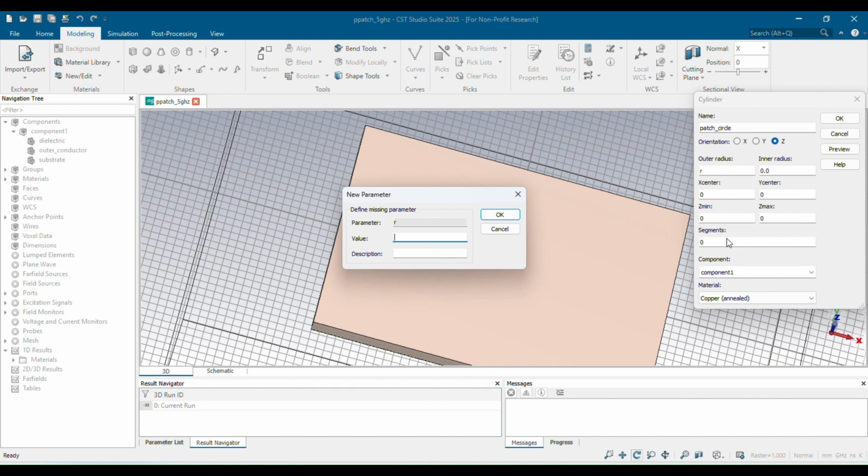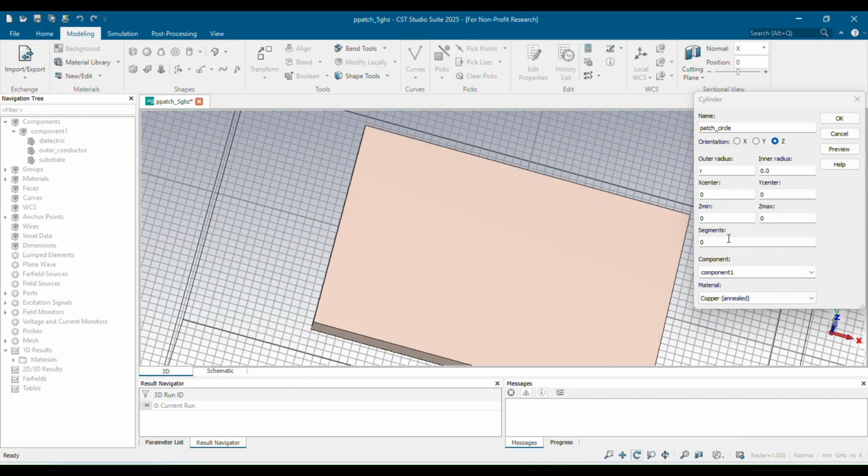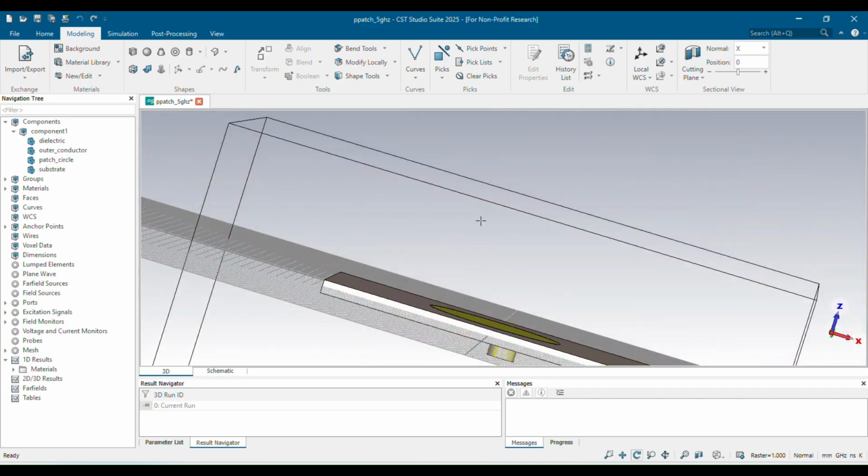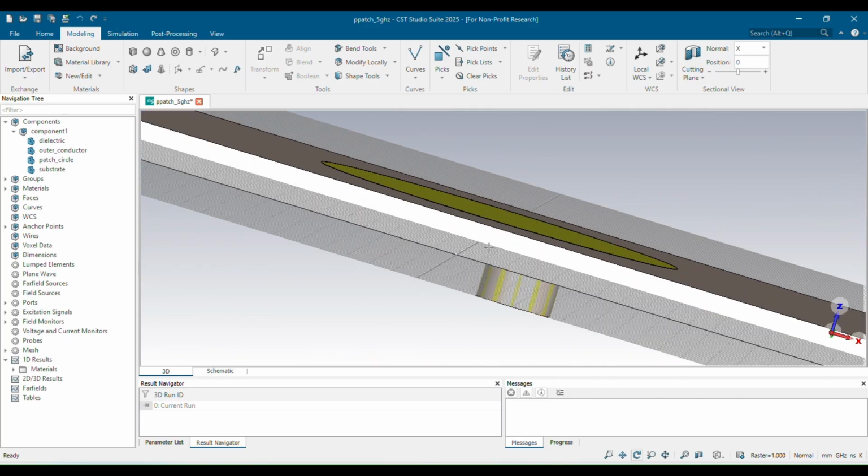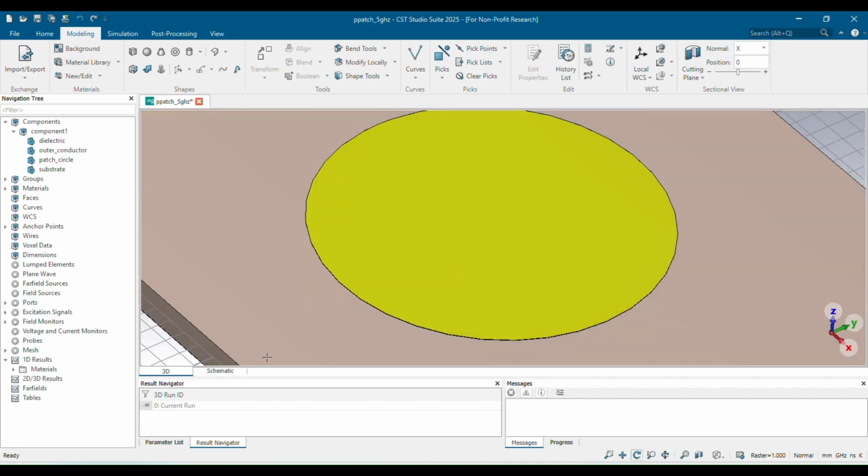With respect to a circular patch antenna, all we can change is the coaxial feed location on the patch, because from 0 to r the impedance varies from 0 to 200 ohm, and the radius defines the resonant frequency.